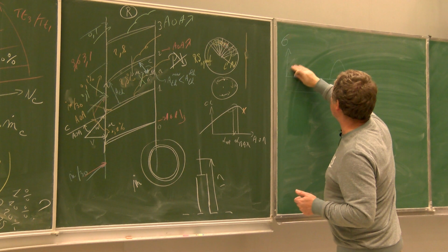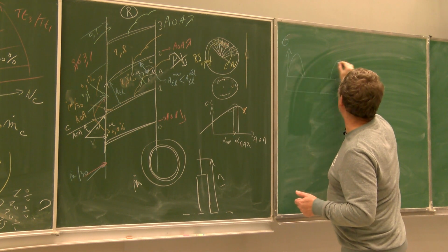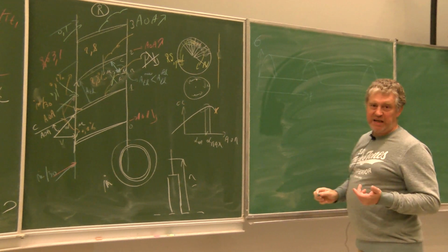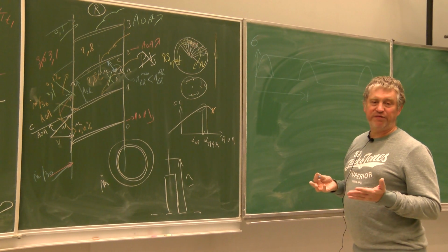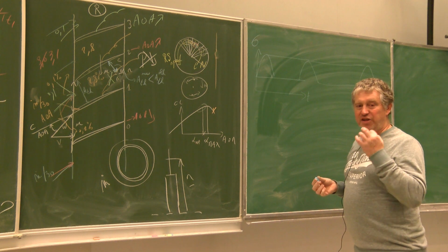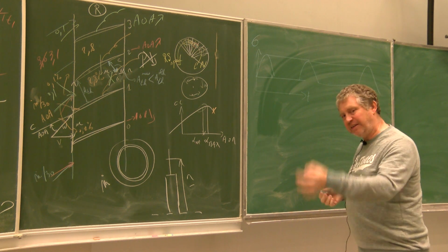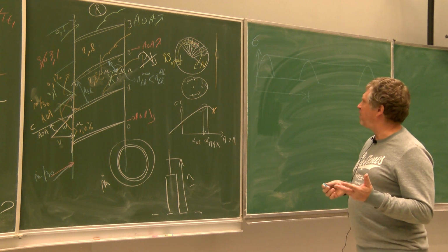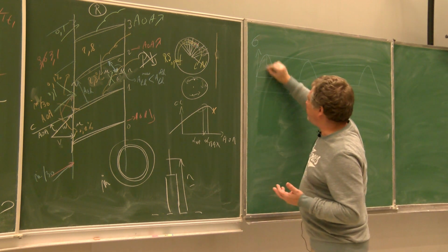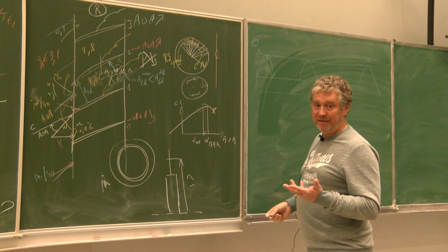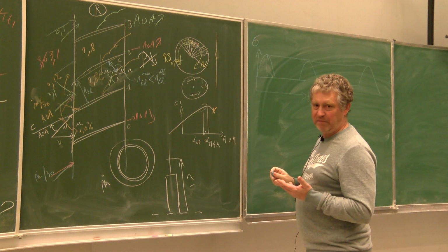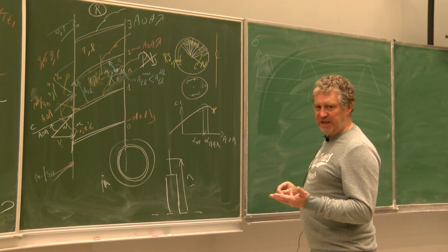It's the same, of course. So the same, and then coming back. And what you see is an increase of the load at some specific moment, each time this rotating stall cell is coming. You have an increase of sigma, which is bad, but mainly the problem will be the frequency. It's related with the rotational speed.